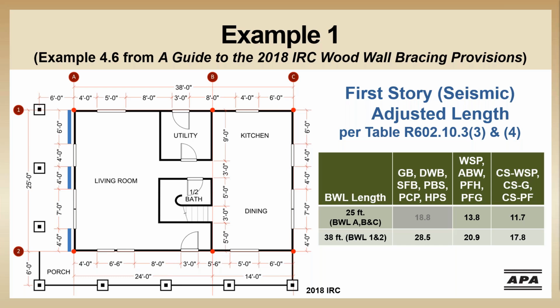And we're going to definitely need that center braced wall panel this time. If we look at braced wall line B next, we could use all of the available wall and we would just barely exceed the required length for column 1. And then braced wall line C is going to look exactly like braced wall line A. In the other direction, braced wall line 1 has 26 feet of wall available, and that's going to rule out column 1.